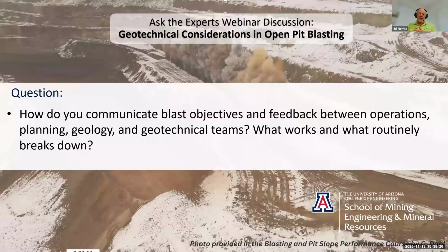And lastly, we've got the tech services. We've got geology, geotech, and the associated survey groups. Their needs are related to the control of blast vibration levels at the wall, trying to achieve the design criteria for effective berm widths, minimize crest loss, and the integration of all the technical side of things into the blasting process.